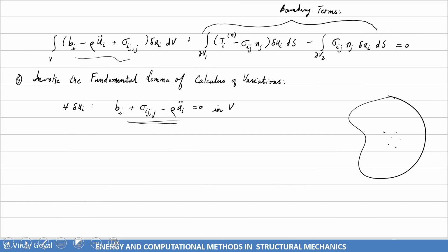And the boundary terms tell us on the surface, on just V1, just on this one here, where I had tractions applied, and on the surface here, this is specified, the deflections, so that's partial V2, and the rest of the surface from here to there and from here to here, I'm calling partial V1, and that's where tractions are applied. Look at this powerful thing here. We get t_i n equals sigma ij nj.